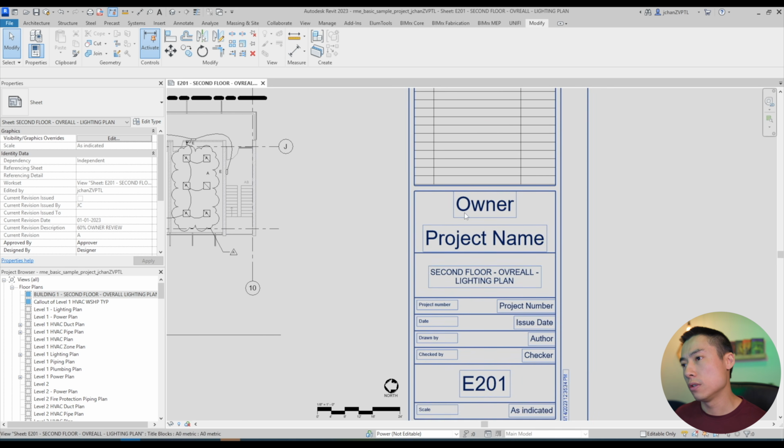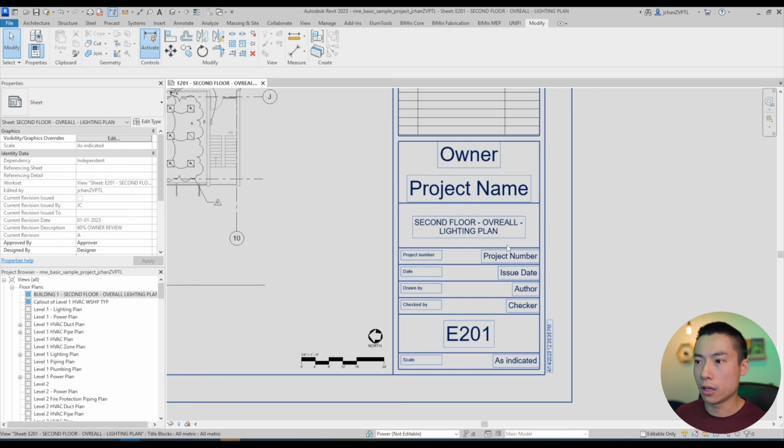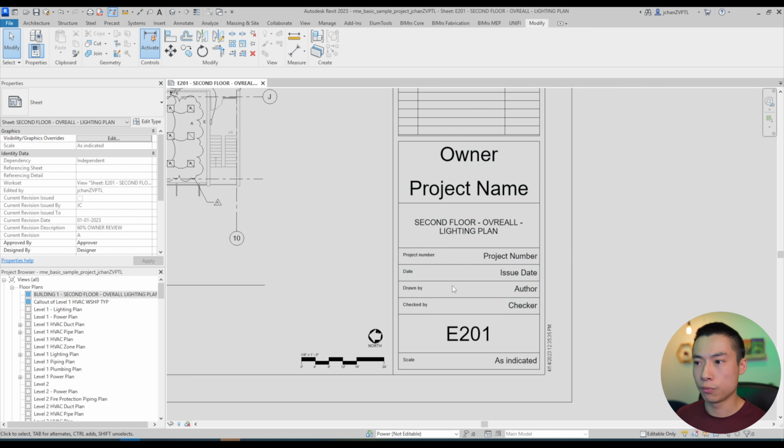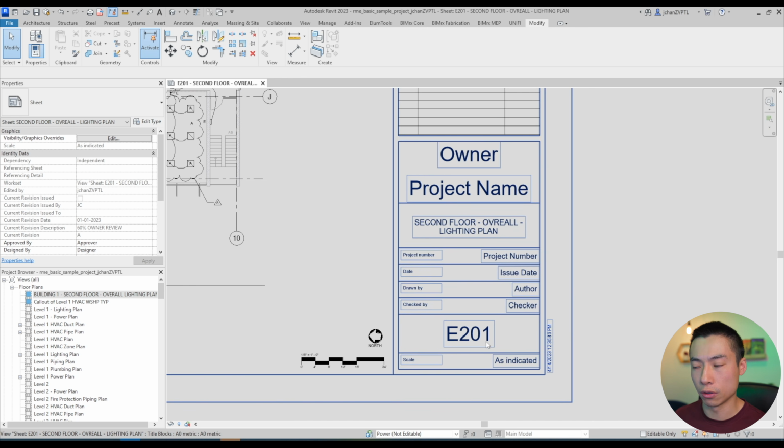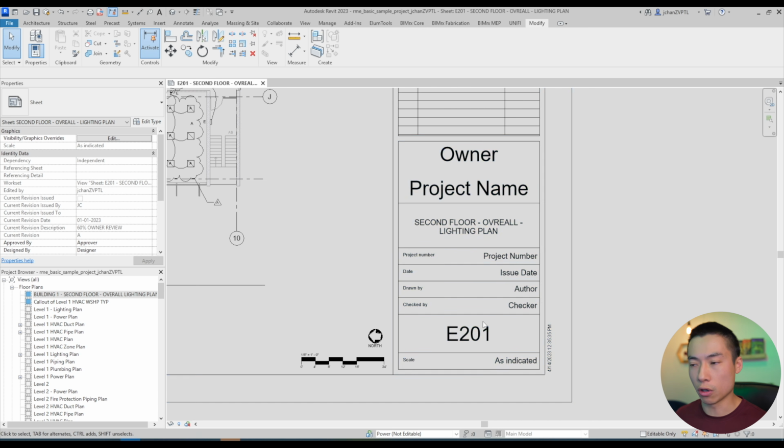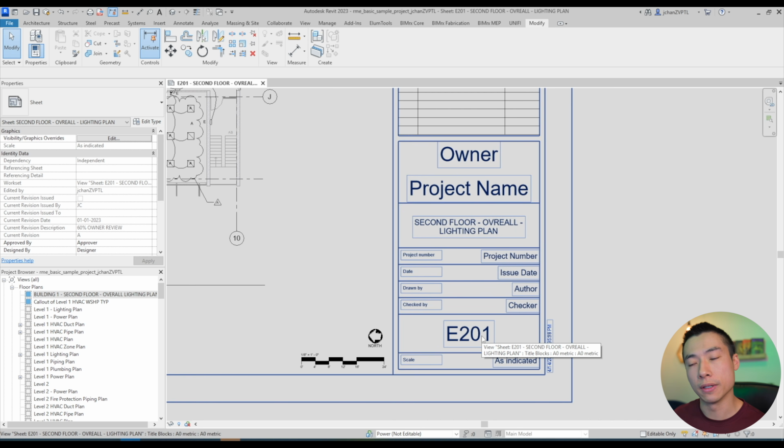Okay, so moving on down, after the revision block, here we have the owner information, the drawing name, project number, who drew this, who designed this, and the drawing number. This is all stuff that you have to make sure is accurate, of course. Sometimes there are addresses on here, and there are changes in the personnel working on this, so this is updated by drawing to make sure it's always current. The drawing number is very important because if you reference anything from another drawing, this is the number that people are going to be looking for.